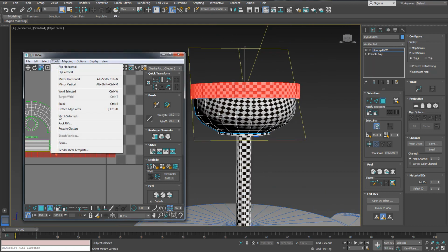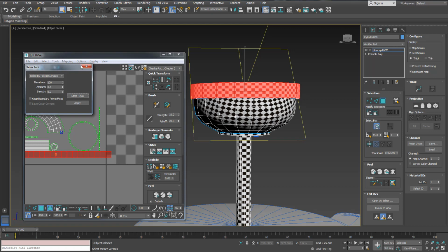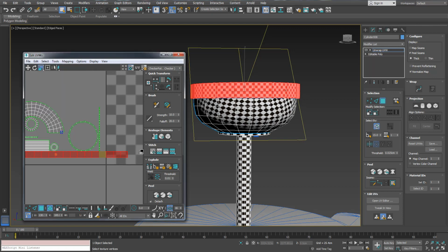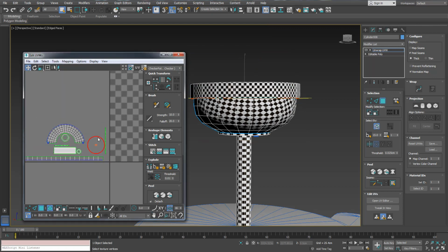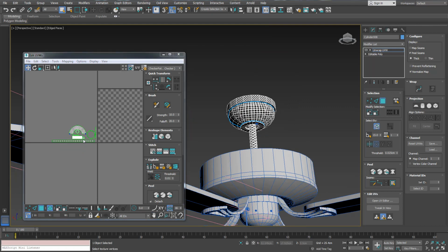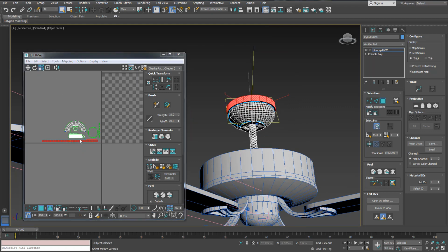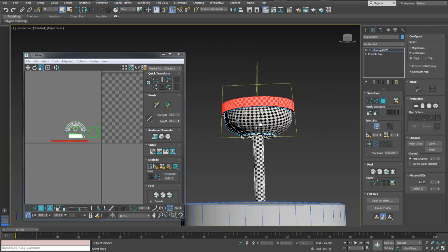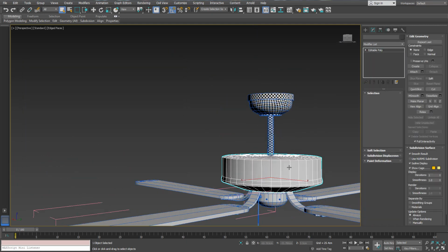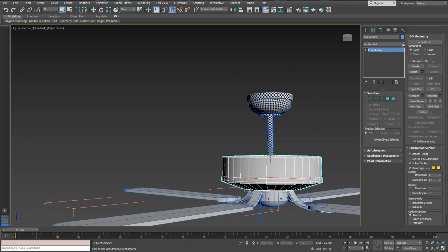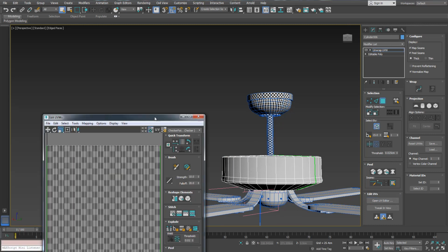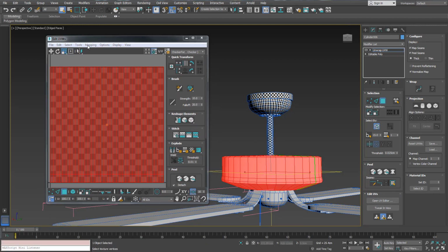Of course, sometimes we need to fix some UV shells or UV islands because it's not going to be perfect. And yeah, the checker texture is very helpful when it comes to telling us if there are any distortions, if there are any problems with the mesh or something of that sort. It's going to be very important.